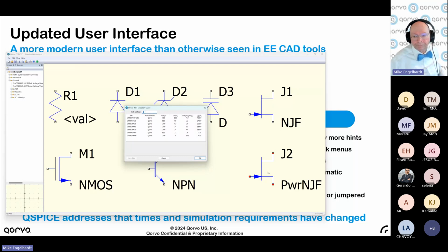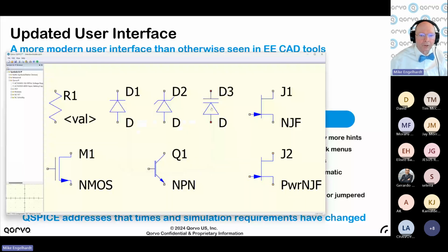But in making nuclear instrumentation, I put as much as a few hundred microamps into a JFET to get more gain. But in silicon carbide JFETs, you can put 2 volts forward, and you still only have a picoamp of current. So let's put 2 volts forward here, and here you can see that this JFET is a 750 volt JFET and a 4.3 milliohm on resistance. So these selection guides will give you a fair bit of information about the different devices.